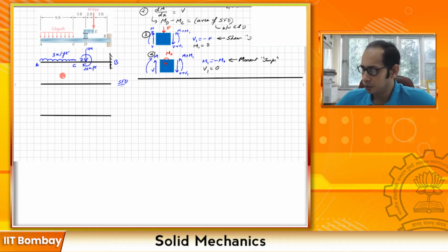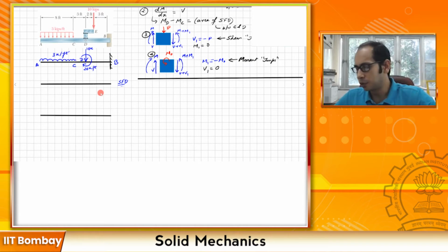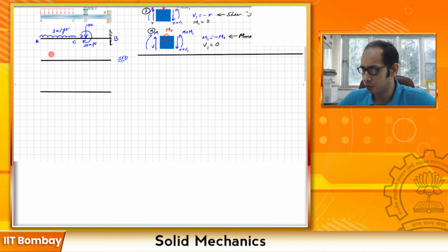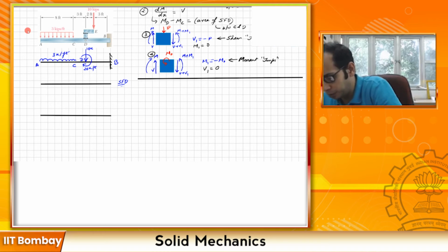When we are dealing with the shear force, essentially we have one relationship here, relationship 1, relationship 3. Let's see which one to make use of. First you have this uniformly distributed load acting from A to C. Let me draw my guidelines as well, to help me draw neat shear force and bending moment diagrams.